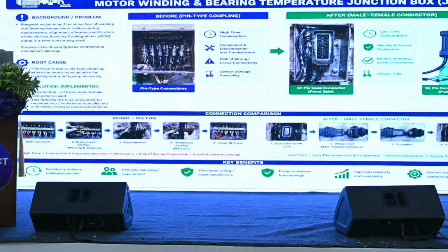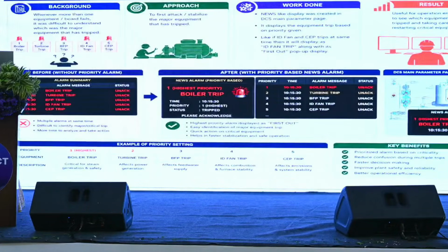And again it is a trial run, not the actual run. Now they go for the trial run, again they observe some defects, and again you have to remove the cables and give them to the maintenance. These are screw type terminals. Each time they are screwing in and screwing out, the terminals will get brittle and break. And a lot of human errors are possible because there might be misconnection. So these terminals were changed to pin type, so that now we just do plug-in and plug-out, and all these errors can be reduced.